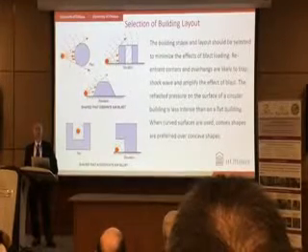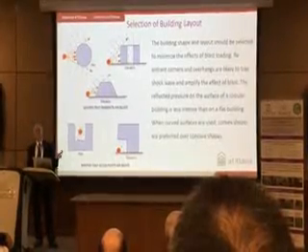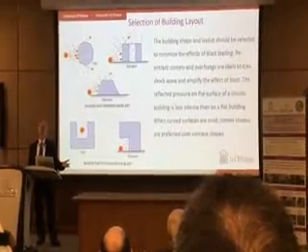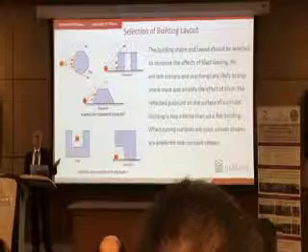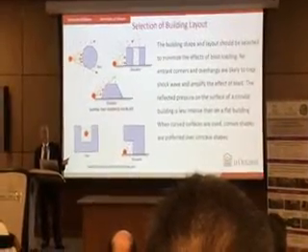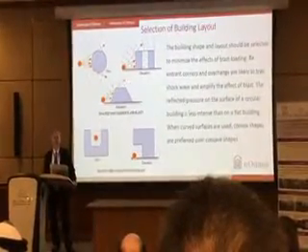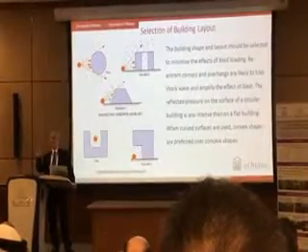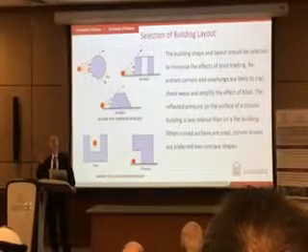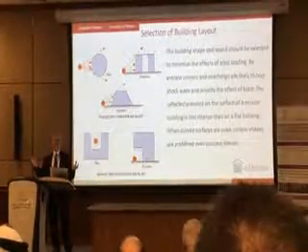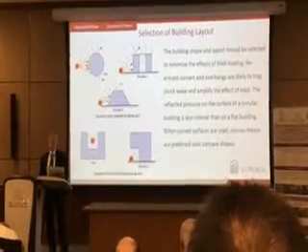We were involved in assessing a Jewish school in Montreal, and they said that they wanted to build a school on top of a public garage. And they said, what if there's an explosion in the underground parking? You have to protect our structures. I said, this is a very big challenge. They said, no, we want you to show us if it's a challenge. So my student did dynamic analysis. He came up with 2-inch thick steel plates to put around columns to protect them. Even then, it didn't work. Why? Because this reflection of blast shock waves amplified the problem. So confined environment as opposed to unconfined air attack are two different things.